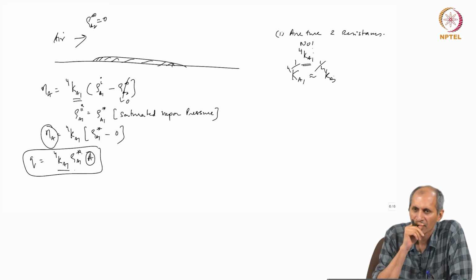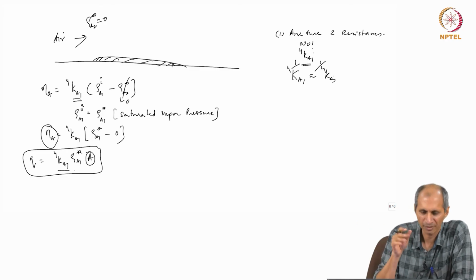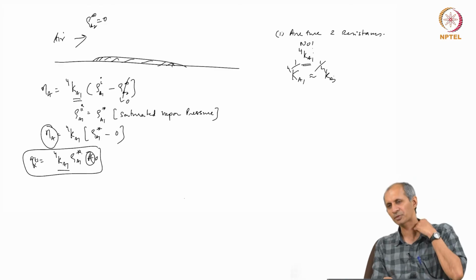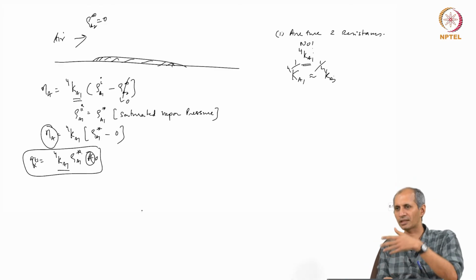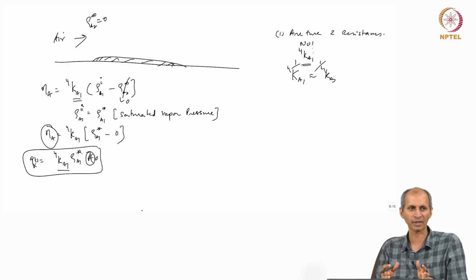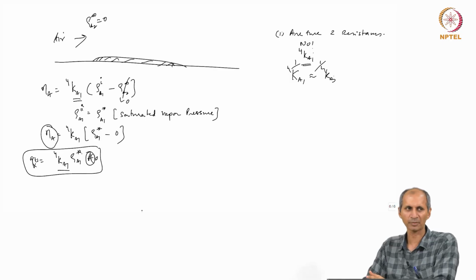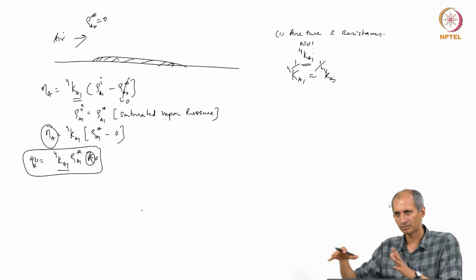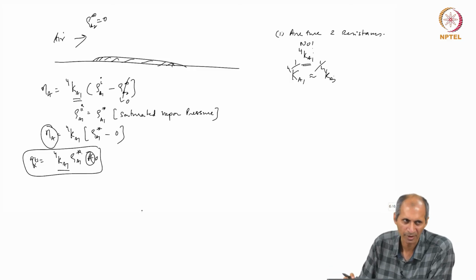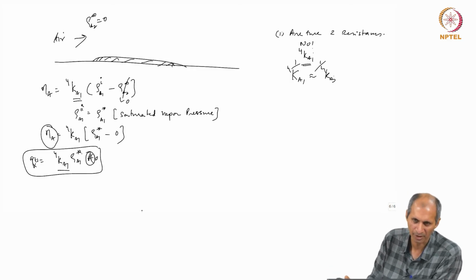The moment the area is changing, you have to change your Q value. If area is a function of time, Q will also become a function of time. But the dispersion model is not set up to do unsteady state problems. So, you have to break it up into small times. You will say from first half an hour area is this much, or average area is this much, next half an hour area is this much, and so on. So, you can do the calculation for that one set and then estimate what is going to happen, and that way we can do.